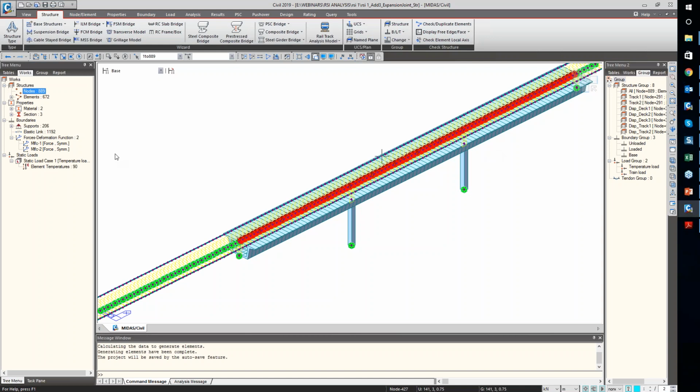So, what about the derailment loads on the concrete bed? Basically, this rail structure interaction is a check. Once you have designed the bridge, after that we check whether my bridge is passing for rail structure interaction or not. These derailment loads, curvature loads and all the other types of loads we need to consider during design. So this is a post-design kind of check.